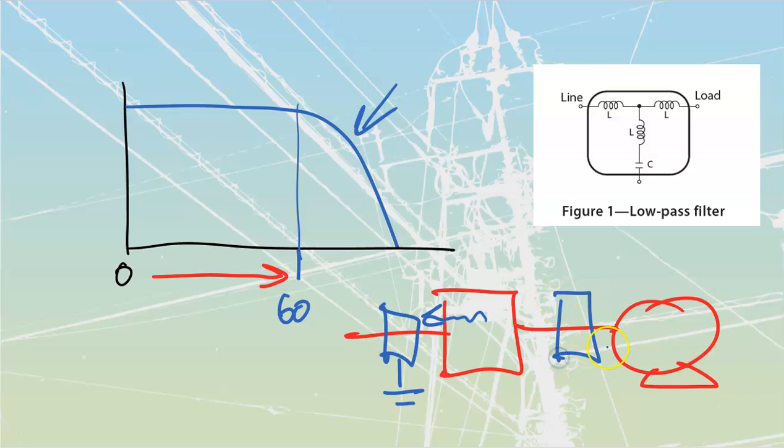You can place them on both sides of your VFDs. At that point, you'll be protecting your motor from a lot of your higher amounts of harmonics, etc. You're also going to be protecting the rest of the installation, because then you're not dealing with radiation coming off of these lines that would otherwise be out there acting like antennas. They're very cheap compared to a lot of our other fixes that we have out there. In some cases, they are built into the drives themselves, that they're going to have a low pass filter. That's always a very good thing to see on a drive list over there.